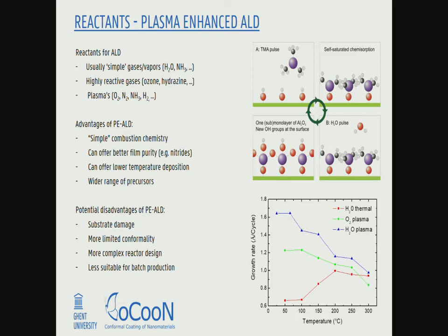Very briefly, I will only spend one slide on plasma-enhanced ALD just so that you know that it exists. The potential advantages of plasma-enhanced ALD is that for this second step here, you get to relatively simple combustion chemistry. You don't have to rely on very nice chemical reactions with the remaining ligands on your surface. Whatever is carbon will just be combusted off. So in that sense, it's simpler and very aggressive chemistry.